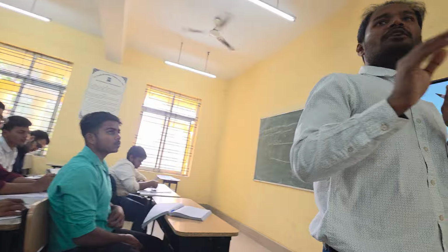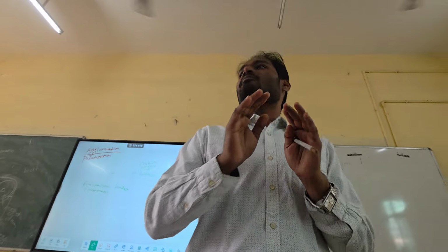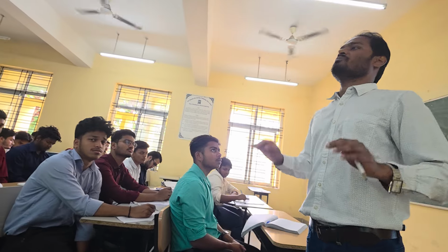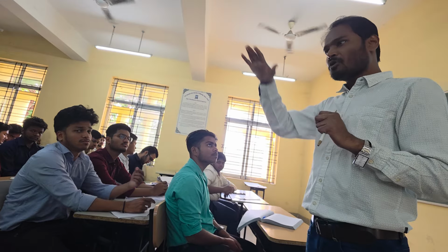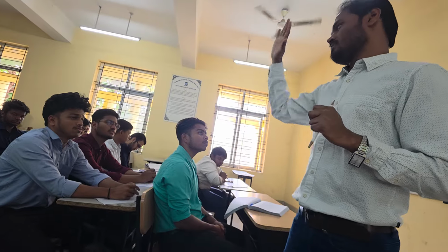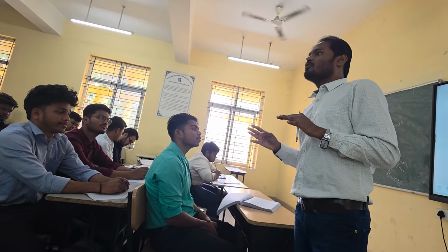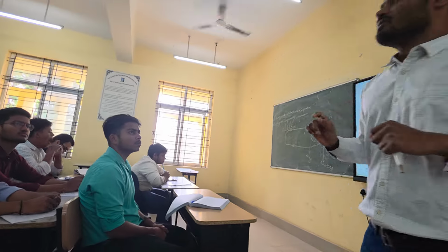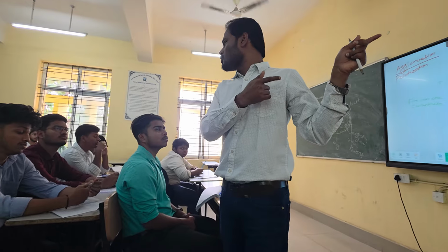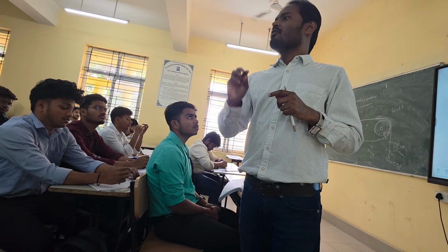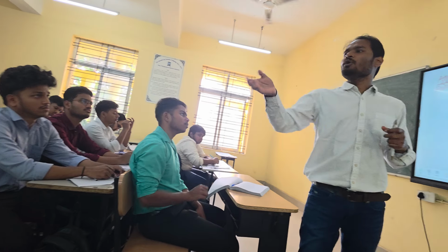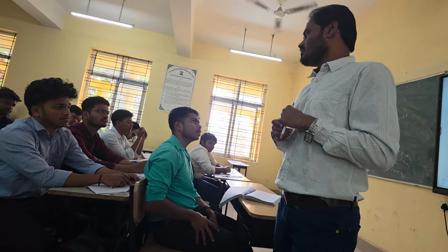We see, this is very important. We cannot run a blast furnace or a counter current reactor without having permeability, because some mass needs to go down, some mass needs to go up, right? You need permeability. You cannot run a blast furnace without permeability. So okay, I will not go into details in that. You understand? So pellets are good. They are uniform size, they are spherical, and they don't need any kind of crushing in between after preparation.